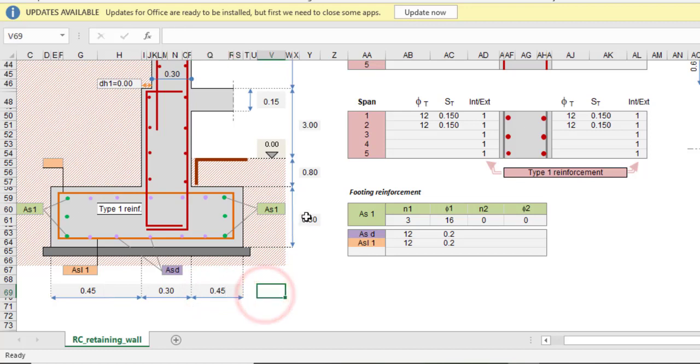All right, then I will now make my foundation equal to 1.5 meter. Don't forget that the foundation will start from here. So if this point is 0.3, you just have to remove 0.3 from 1.5, and then you'll be left with 1.2. So I'll make this point 1.2. Okay, so at the end of the day, when you add 1.2 to 0.3, what we buried under the ground will be 1.5, and that is your foundation depth, of course.